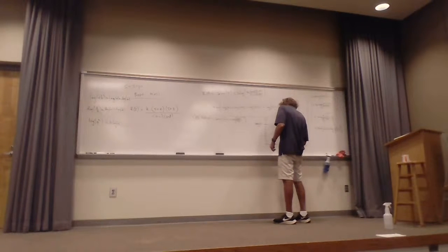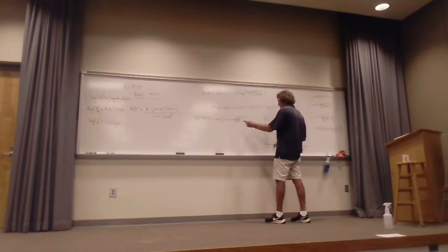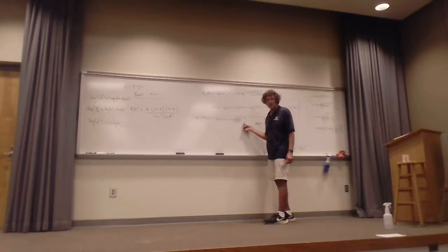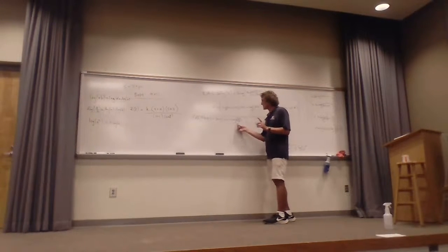If this is A here, then until you hit omega equal A, this would be a straight line. When you hit omega over A equal 1, now you get 1 squared plus 1 squared, right? Or the square root of 2. Do you follow me on this? Now just listen to me carefully on this. 20 times the log of the square root of 2. The square root is really 1/2, right? You can take the 1/2 in front. It's 10 times the log of omega squared, or really of 1 plus 1, or log of 2. Well, 10 times log of 2 is 3 dB. Y'all follow me? It would be 3.